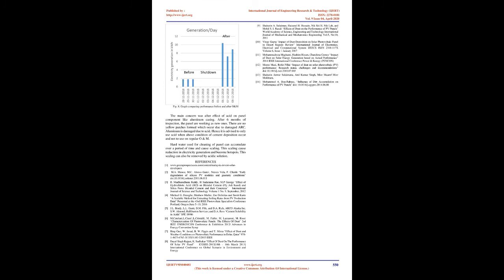Care was taken not to use a metal scrubber, hence non-scratch sponges were used to clean the panel after thoroughly cleaning using the solution. The panels were washed again with clean water to remove any other residue present. The total time required was 40 man-hours.